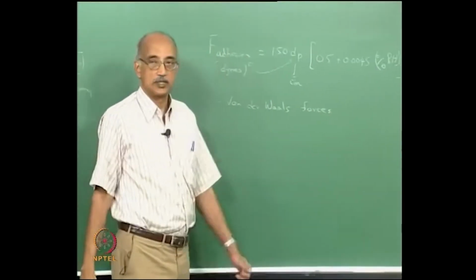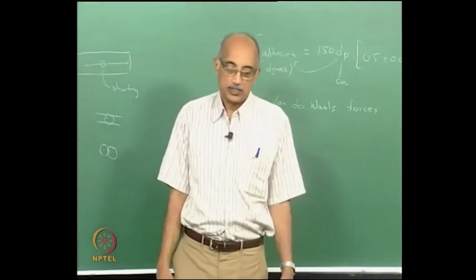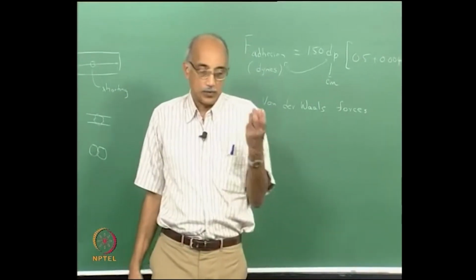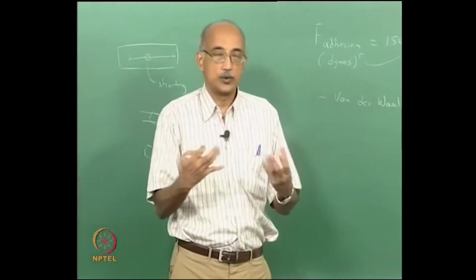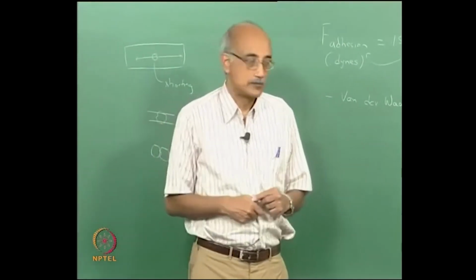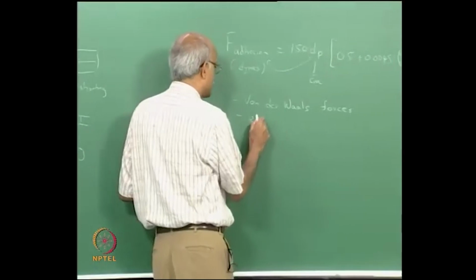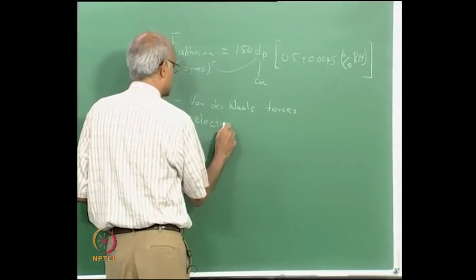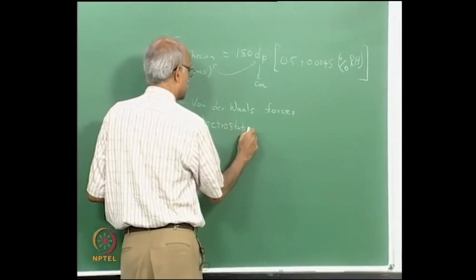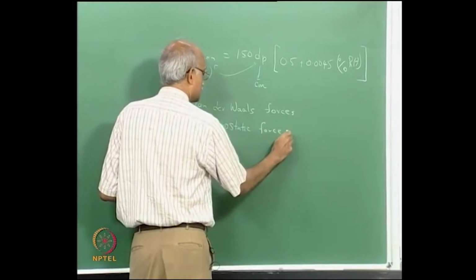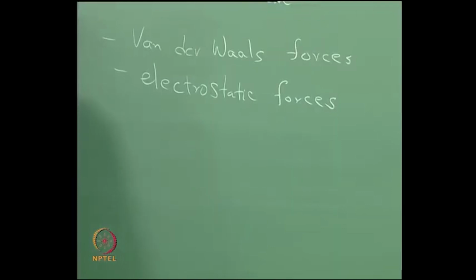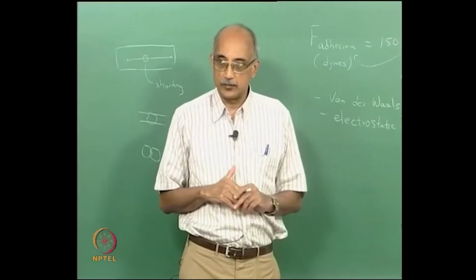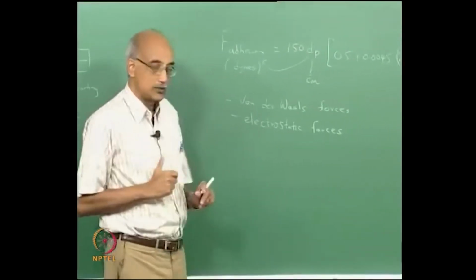These are the forces of intermolecular adhesion which would prevail even when the particle is completely dry and the surface is completely dry, or the two particles are completely dry. The second are electrostatic forces. Again, electrostatic forces would apply even in a completely dry environment, and by the way, when we talk about electrostatic